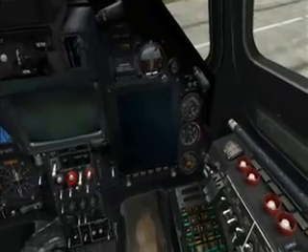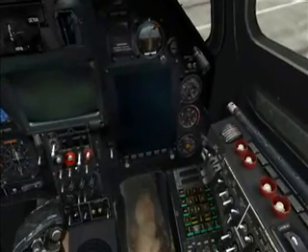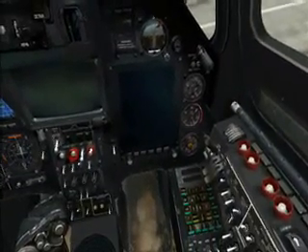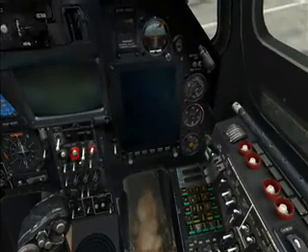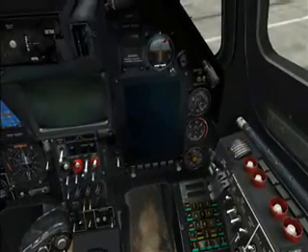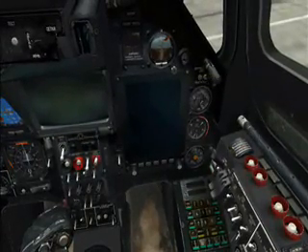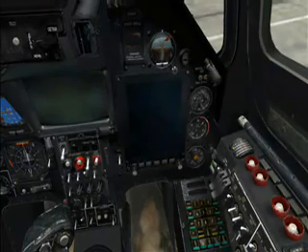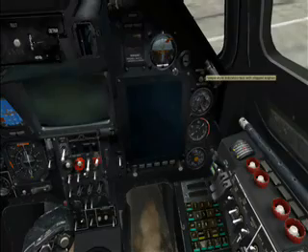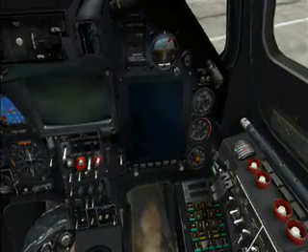And what we're going to be doing is waiting for the needle to get to about 7000 RPM, and then after that we'll go ahead and get the right engine going. While doing that, we can test the engine temperature exhaust gauges, the low end and the high end, and that all looks fine. Okay, so we're at about 7000 RPM, so we'll get the right engine going now.